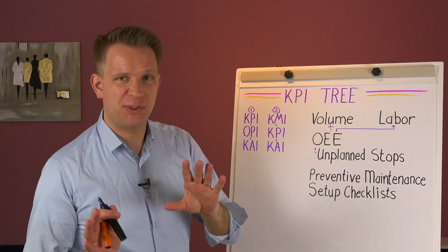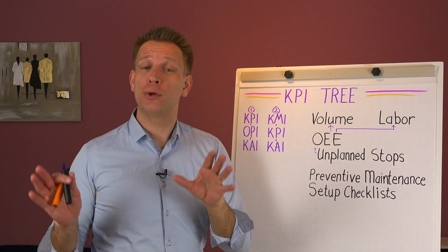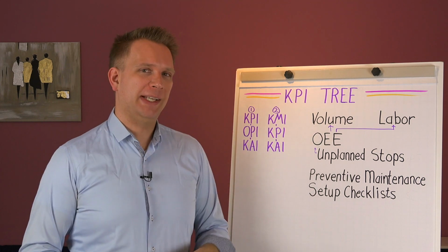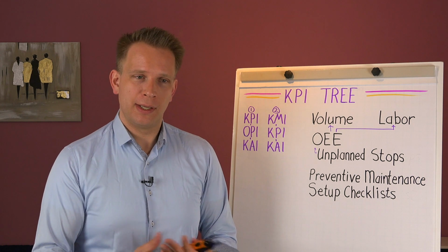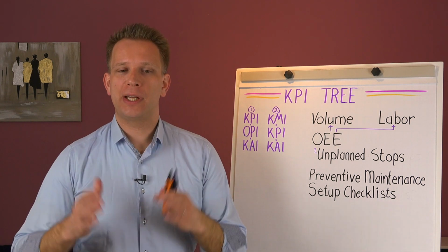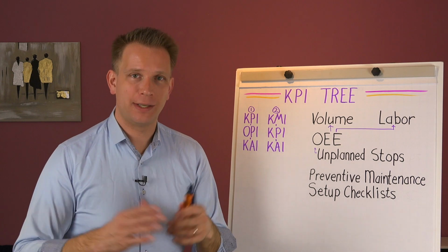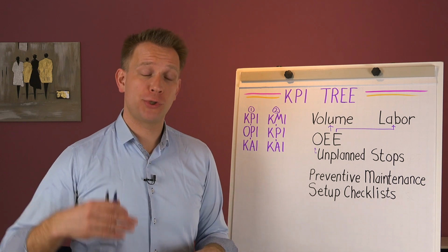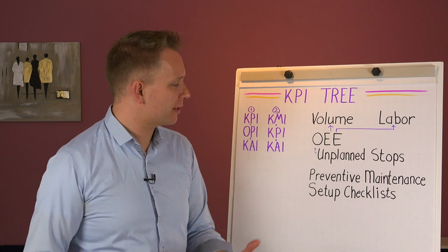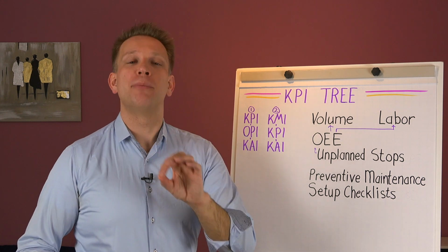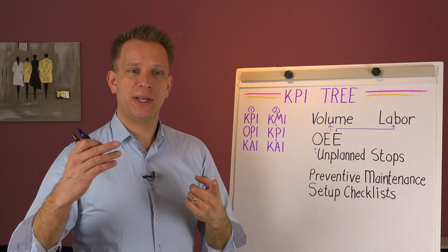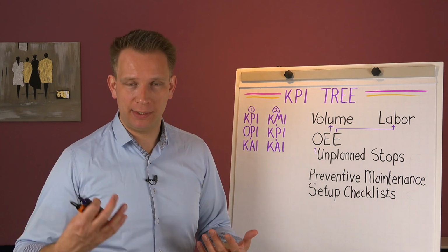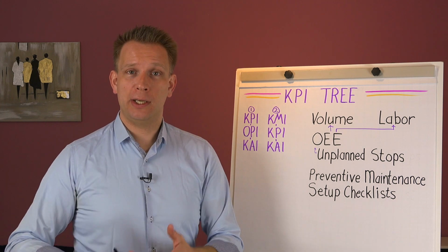It might, especially at first, cost a bit of OEE. Preventive maintenance is definitely also one of the time sinks for OEE. But if we have a preventive maintenance plan and we thought about it, then the action indicator is that we actually do it as needed. So we're going to focus on our maintenance department mostly, but also operators that are trained in specific maintenance tasks to do those preventive maintenance tasks, to correctly do the inspections, to react to things, to make sure that our maintenance tickets that are in the maintenance management system are done on time, in full.